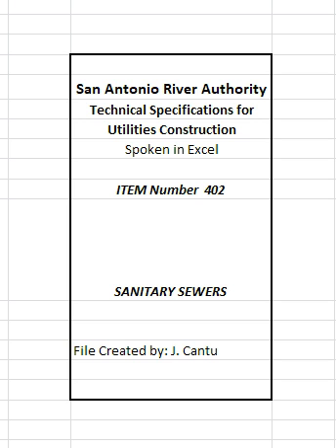Silver recovery units. Silver recovery units shall be installed in waste lines leading from X-ray processing, photographic processing, and any procedures in establishments such as medical labs, dental labs, photo finishers, printers, graphic arts production facilities, hospital facilities, veterinary hospitals, or other establishments where silver may be introduced into the sanitary sewer system. Solids interceptors. Solids interceptors shall be installed when pre-treatment of waste streams is necessary to prevent solids greater than 1/2 in diameter, which may cause line stoppage from entering the sanitary sewer system.